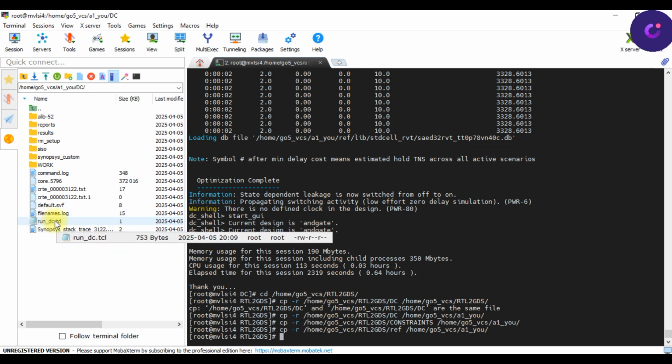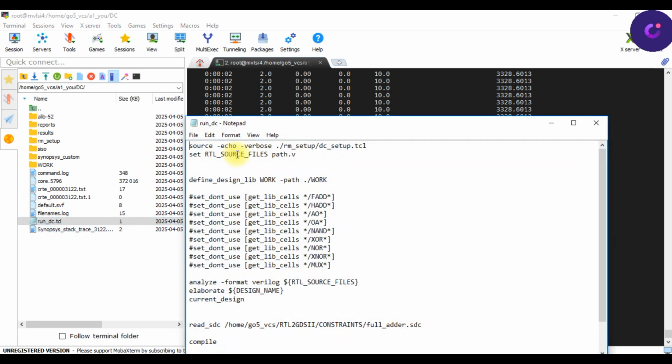So we have to run this file, and all the libraries will be added and invoked, and it will be run by this Tcl command itself, the script file itself. The only thing we do is provide the path for each source file, and one by one the Tcl commands will be executed, and with that the synthesis process will also be done.